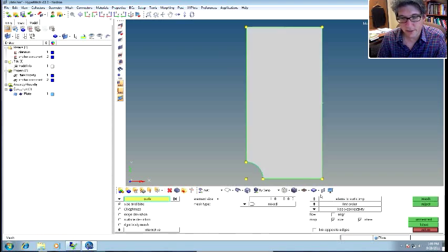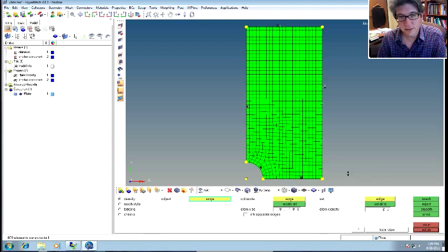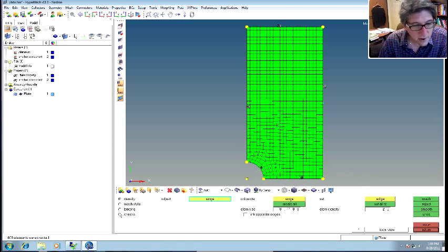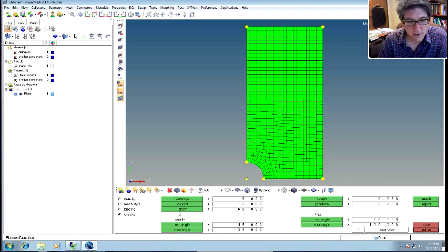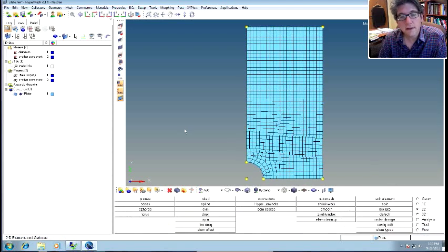So we're going to do auto mesh because there already is a surface. Let's set the element size to 0.4. Okay, and then they're going to be mixed, and there we go. First order elements, and we mesh, and there we go. But in here, I think, okay, I can do the checks here, actually. You can do the checks directly here, and we can check the Jacobian. And they all pass. Actually, the smallest Jacobian here is 0.78, so that's actually an excellent mesh quality. So we'll go with that, all right? Okay. So there's our mesh, okay?